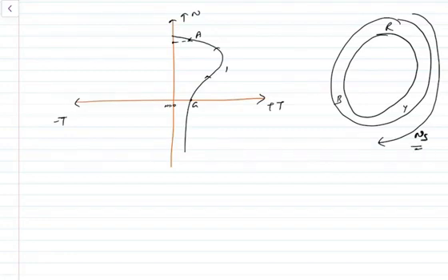Let us assume any two phases are interchanged. Let us assume phase Y and phase B are interchanged. That means this Y is replaced by B, and this B is replaced by Y. That means you have reversed any two supply terminals. It can even be RY or RB, any two terminals.